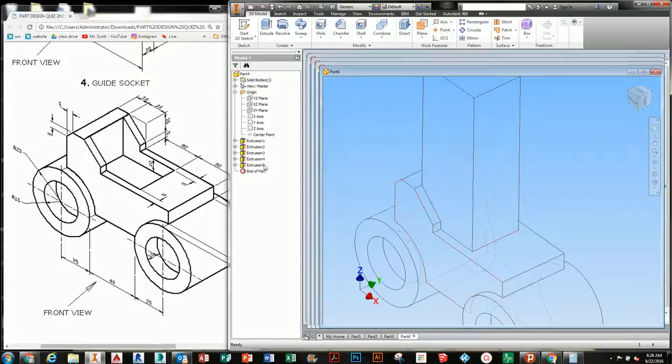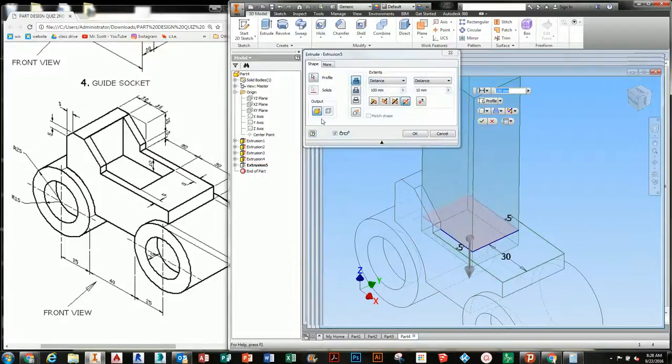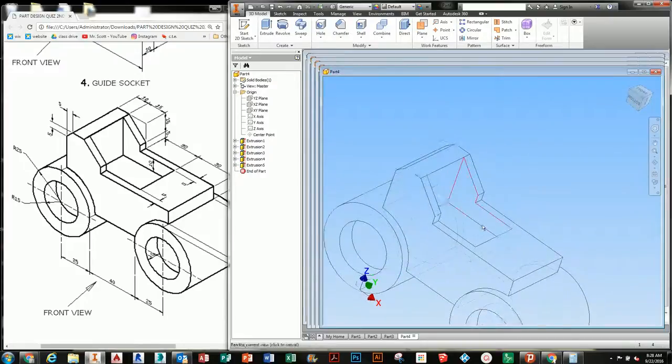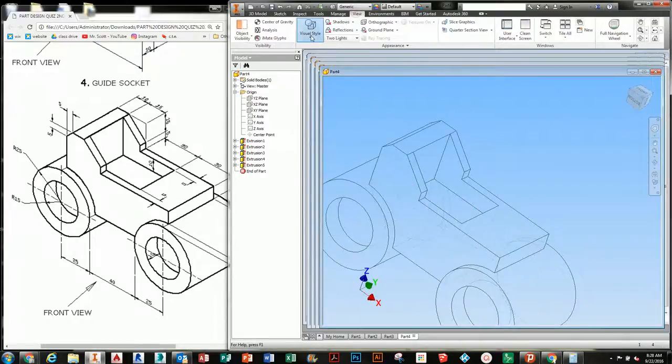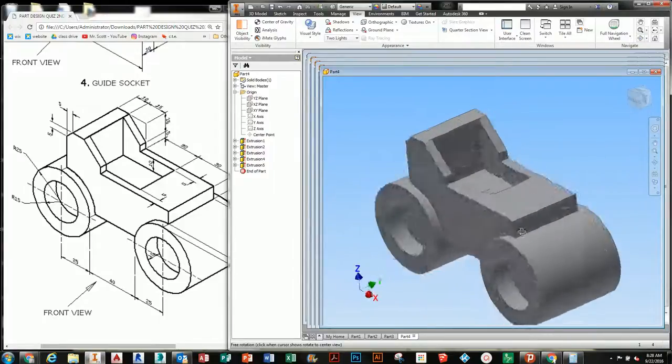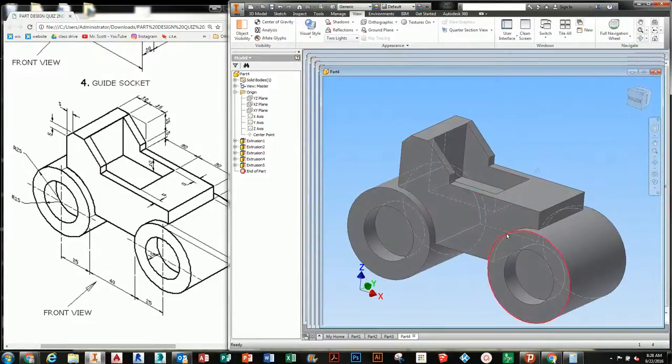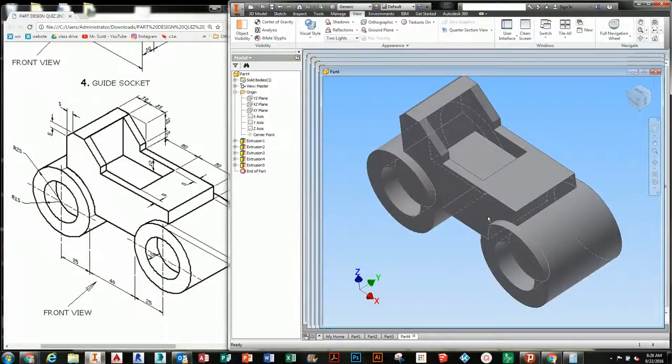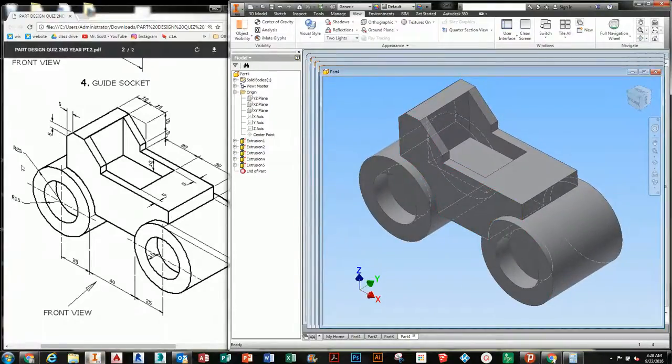Oops. If you ever mess up an extrusion, just open it back up, turn it to cut, and it'll fix everything for you. Then you go to View, change your visual style, and make sure it's coincident and follows the object you've built. And make sure you save each of these files, and you'll place them on a drawing with dimensions and move on.